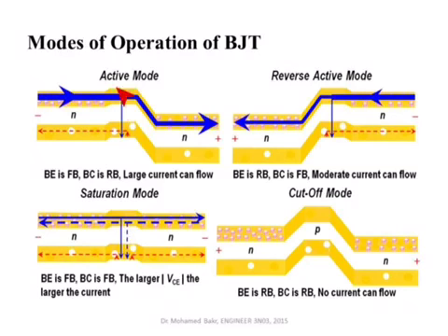When you forward bias this junction and reverse bias this junction, you are moving the energy level of the N-type material of the emitter up, reducing the energy level of the N-type material of the collector, allowing electrons to flow through the thin base, and then roll down the energy level to the collector, or allowing current to flow this way and then that way. This is the active mode of operation, and this is the one we're using for amplification.